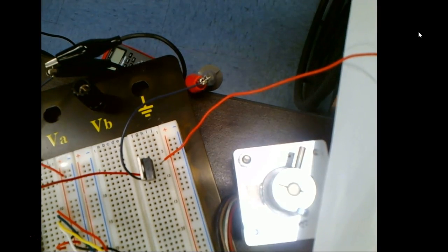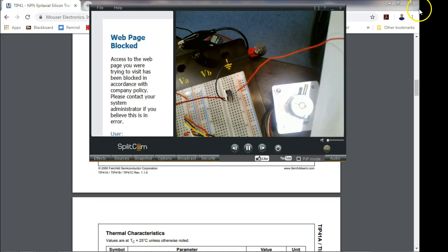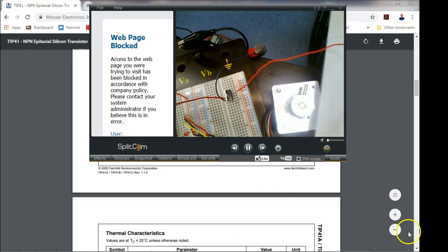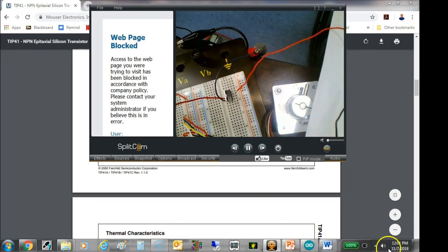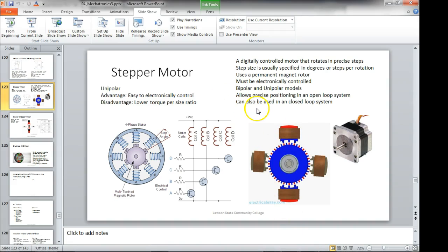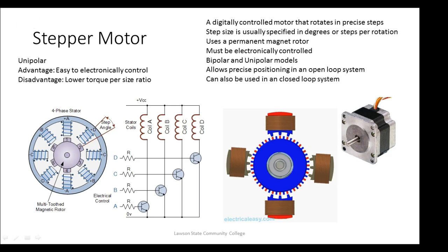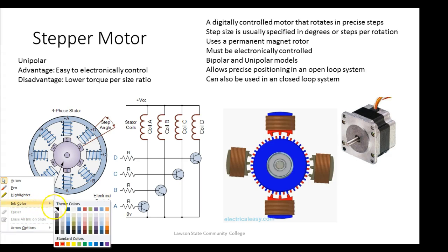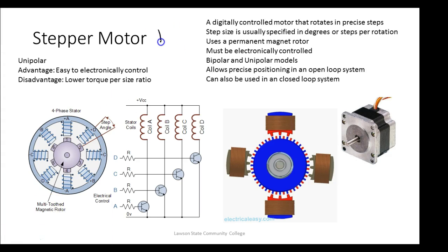It still is going to get warm. The transistor gets hottest while it's switching. So the problem we have is that when the transistor cuts on, it's going to drop 0 volts, or less than 1 volt.